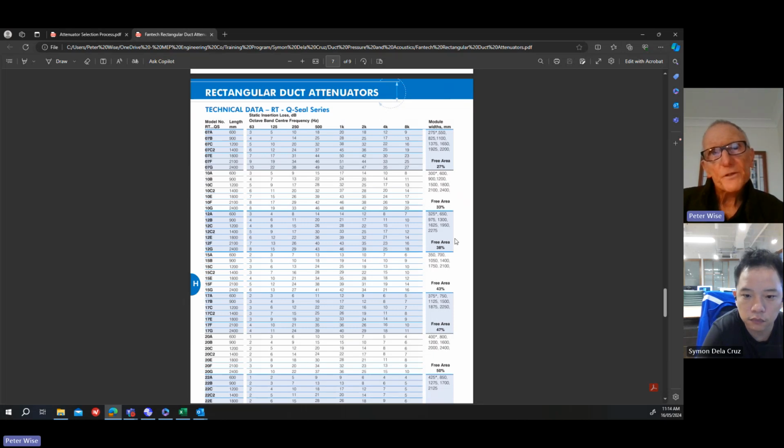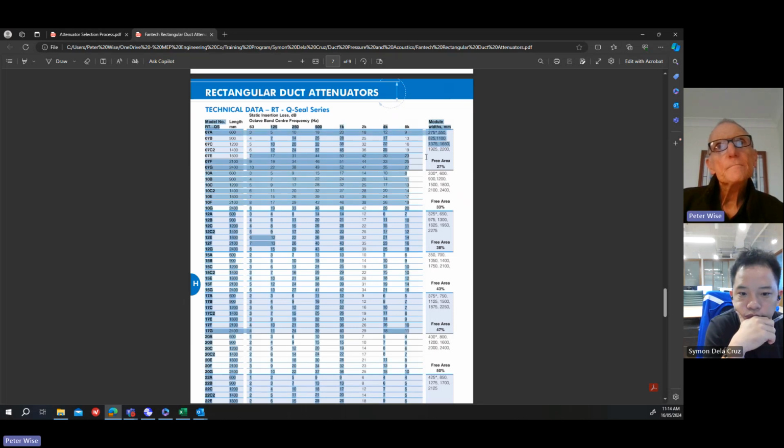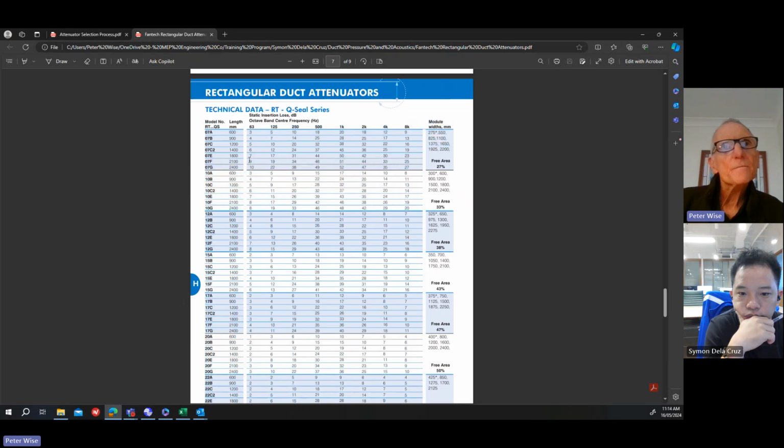But it just depends. So I think I've said to you before in our previous session that the critical frequencies are usually 125 and 250. So what you tend to find is when you're selecting an attenuator, 63 is not so critical, but 125 and 250, we need to achieve those.